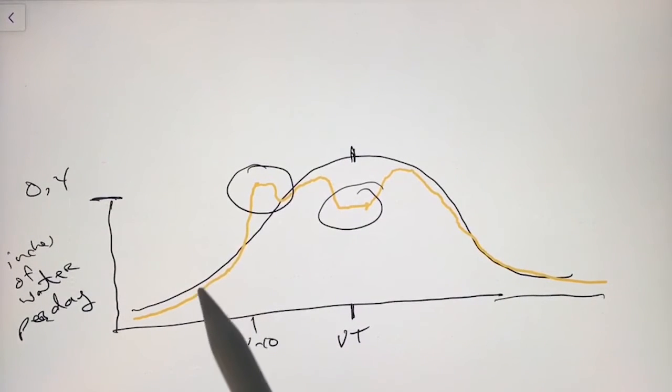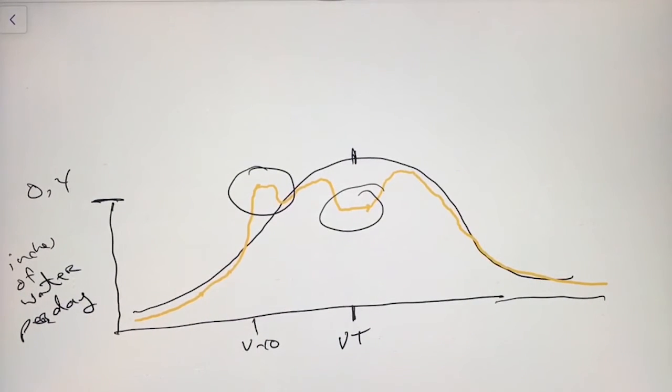We have the average, which is the black line. And again, it's just an average, but it is driven by the crop growth stage. So smaller plants are going to use less water than a plant at that VT to R3 time frame. And then Mother Nature as a whole drives the other components. So we've got temperature, relative humidity, sunlight, and wind, all factors that drive the crop water use for that particular plant in that given year.